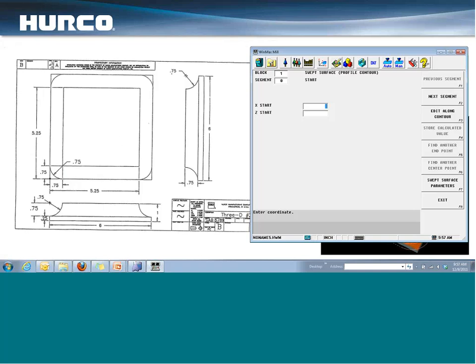Yeah, you could do that. You could program it over to this side if you wanted. But basically, when we define the along contour, we're going to use this here. So all we'll do is define that and then tell it we want to cut on the left side of that line rather than the right. And when we do that, it basically creates almost like a mirror image of the part on the left side of the line. And you'll see that here in just a second.